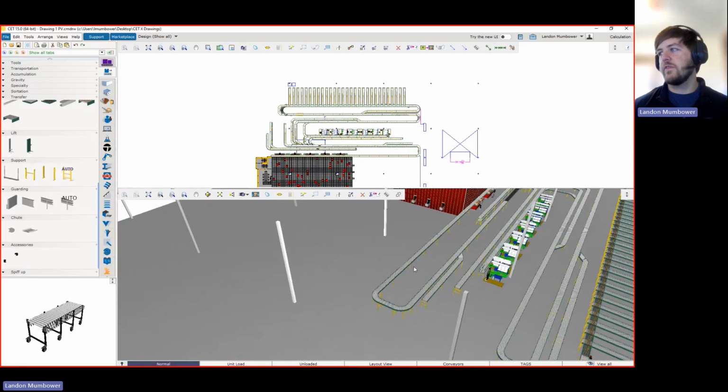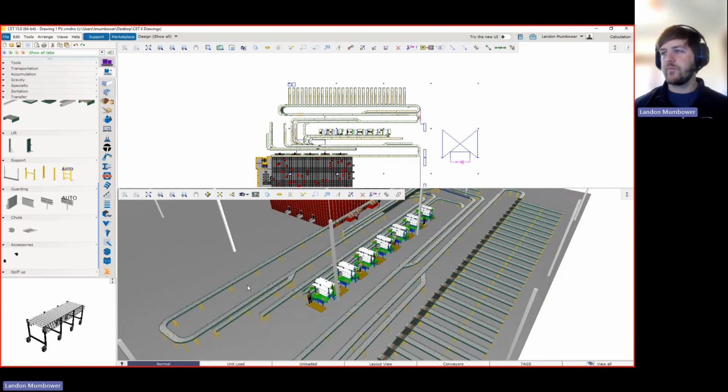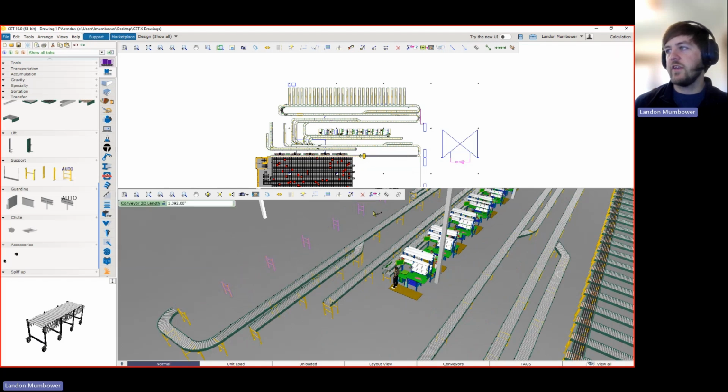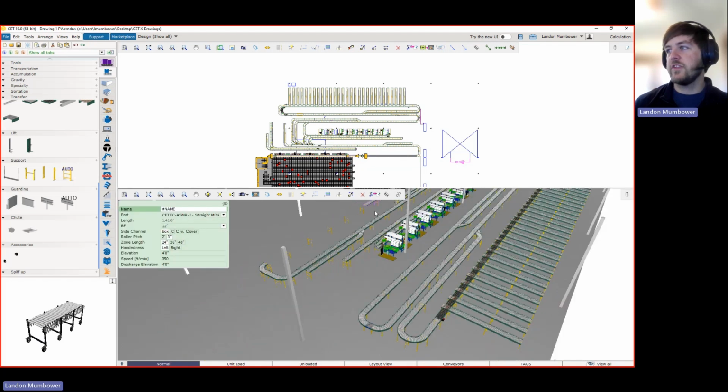Here we go. We're back. We've seen this model. We know what's going on. And let's say we're going to show this advanced selection. So if I come here and I say, oh, I need to make a change to this conveyor. So first I'll disconnect it there, and then I'm going to stretch it down and shorten it down to, let's just say there.